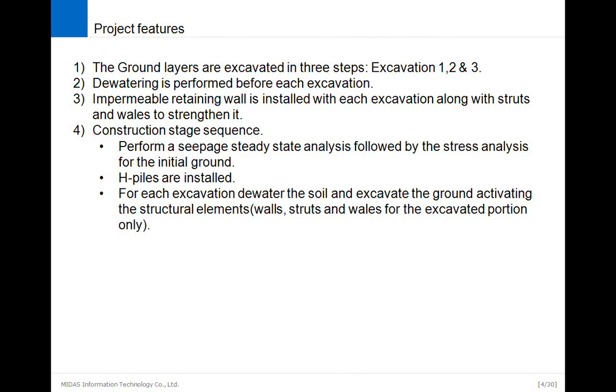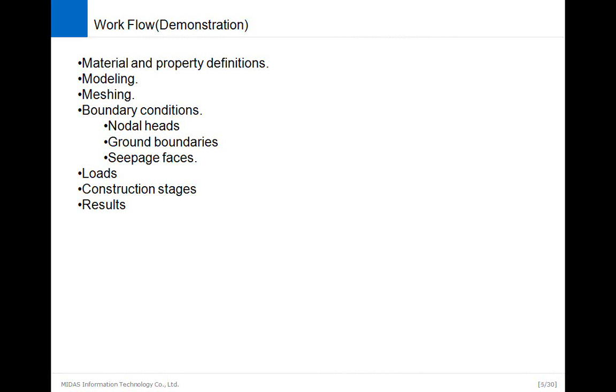And then at the end, you need to ensure that after you have excavated all the material, the bottom has 0 pore pressure, which means you don't have any water lying in there. You have to remove that water. So you have to take care of that thing also, which again we will be talking about in our demonstration.